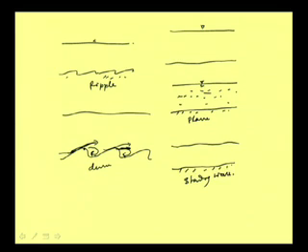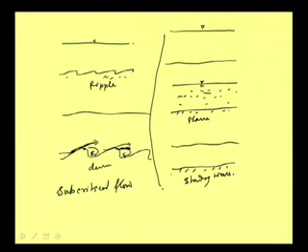So, these are just in transition stage. And one more important point, this sort of flow, that is the ripple and dune, generally occurs in the subcritical flow condition, very subcritical flow condition, that is, the Froude number will be very less here. And this transition takes place when the Froude number is gradually increasing and becoming nearly equal to 1. Of course, it will not be exceeding 1, but nearly equal to 1.